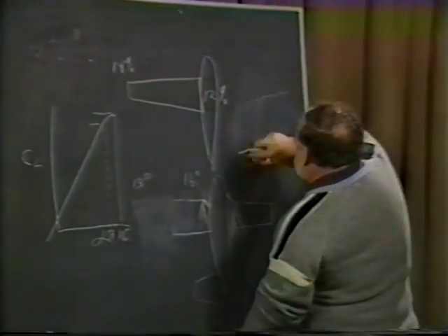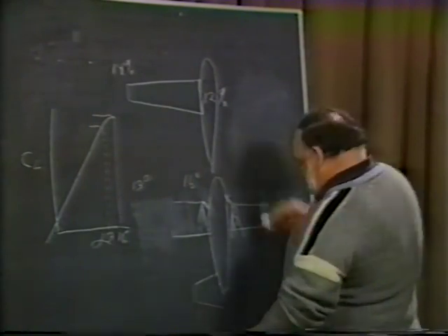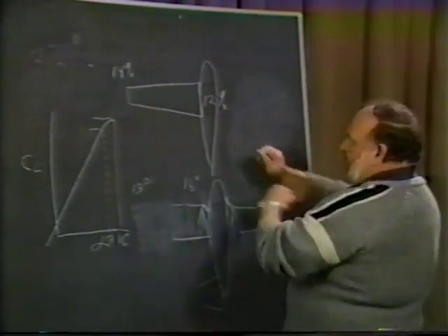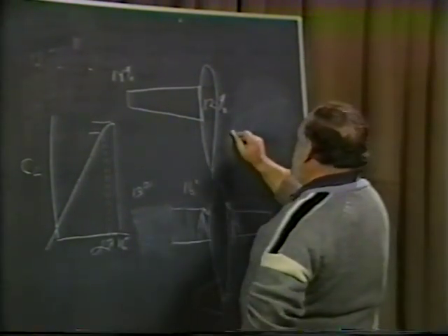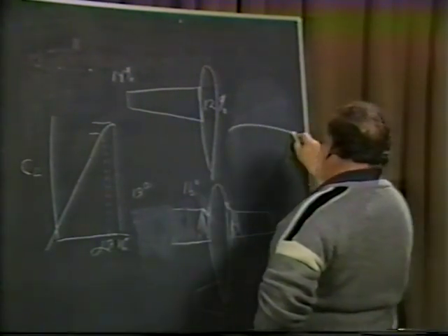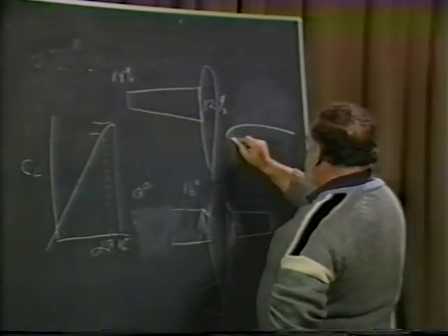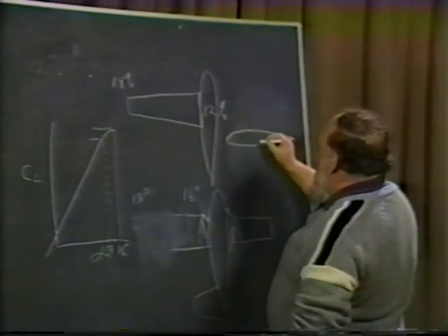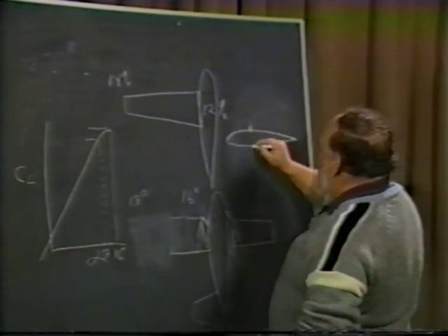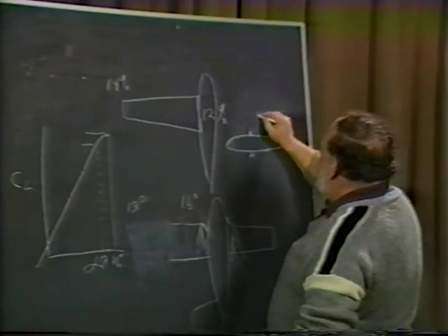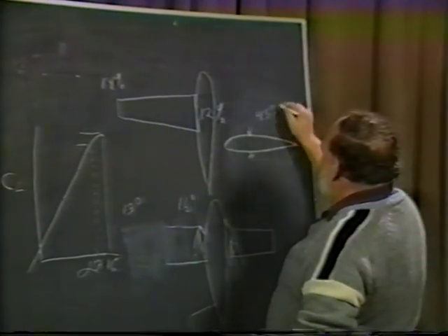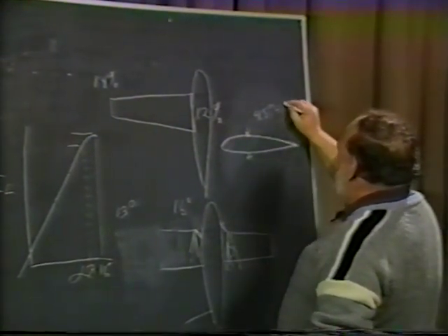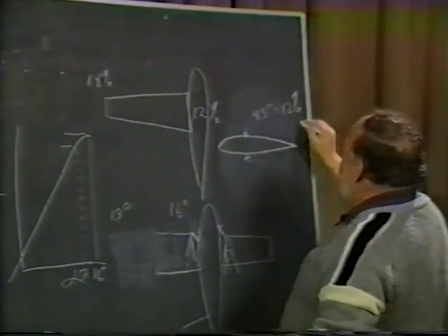and let's draw it over here. Head-on view. I'm talking from a chord line view. If you would draw the inboard airfoil section, it was like this. So this thickness in actual inches, and in this case, I think it came out to be just about 4.5 inches of thickness, which at that point equaled 12%.